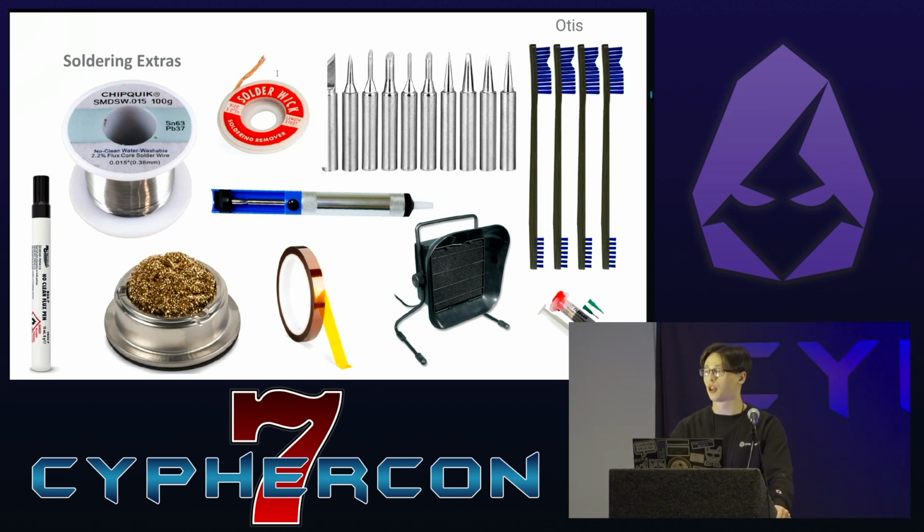And the bottom left is flux. Flux is really going to help through the soldering process. I'm not sure if they have flux over in the Hardware Hacking Village, but if they do, check it out. You'll get a very good idea why it's helpful very quickly. This brass blob in the little silver container is for cleaning the tip of your soldering iron. So you can just run the tip through this abrasive brass, and it'll help keep it clean as you're working.